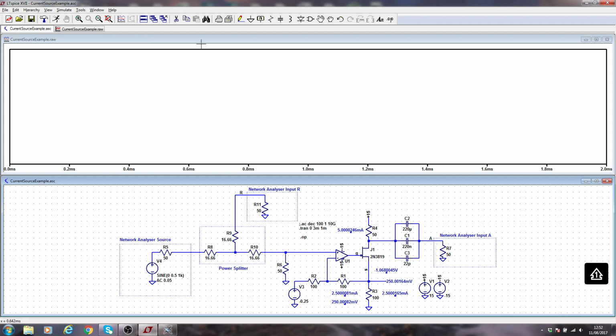When I installed, by the way, I changed all the colours. So if you've just installed it fresh, the background will be grey. There probably won't be any grids on. If you want the grids on or off, it's Control G. That's different from if you want a ground, where you just press G for the ground, but Control G is the grid. And I make the background of the graph pane white, and I change the colour of the graph traces as well. Also, I make the lines thick. I'll show that in a bit.